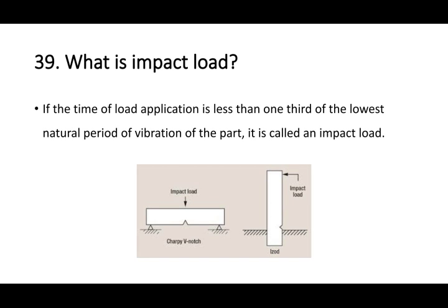Next question. What is impact load? Generally impact load is applied during the Charpy test or the Izod test to determine the toughness of the component. If the time of load application is less than 1/3 of the lowest natural period of vibration of the part, it is called impact load. Impact load is also known as sudden load or shock load.